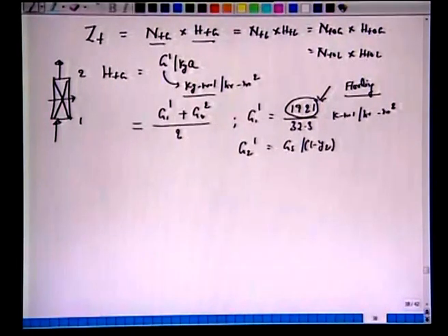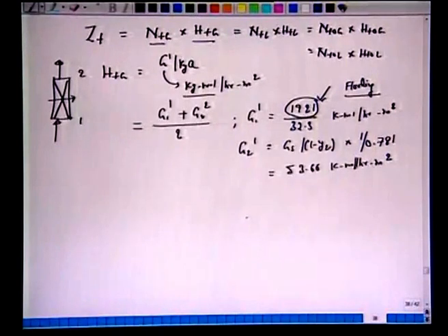All right. So, this is the solvent flow rate, which remains constant at 1 and 2. So, we have GS over 1 minus Y2, which is 1.2 into 1 over 0.781, to give you the same quantities, 53.66 kilomole per hour per meter square. All right. So, what is this 0.781? This is the cross sectional area we got.